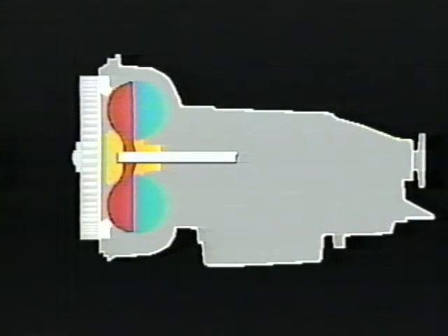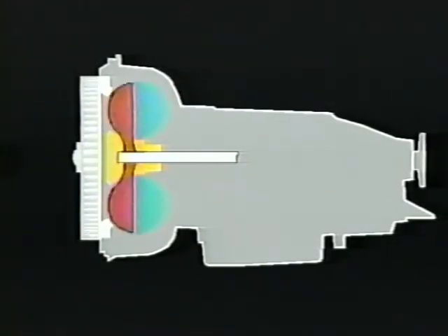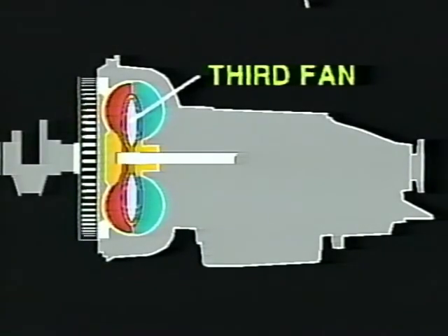Just as with the electric fans in our example, as engine speed is increased from idle, the fluid within the housing will cause a coupling effect to begin between engine fan and transmission fan. At a given speed, dependent on the design of the unit, full coupling will be in effect, and both fans will turn at nearly the same speed. A refinement to this principle involves the addition of a third fan. The third fan redirects the fluid to provide torque multiplication. This design is commonly referred to as a torque converter and is used in all modern applications.